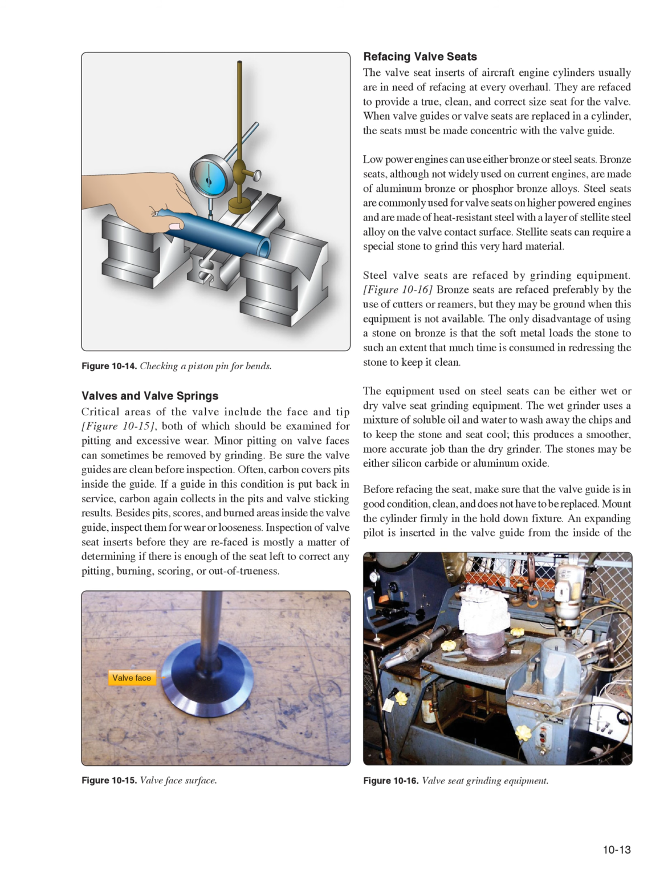Be sure the valve guides are clean before inspection. Often, carbon covers pits inside the guide. If a guide in this condition is put back in service, carbon again collects in the pits and valve sticking results. Besides pits, scores, and burned areas inside the valve guide, inspect them for wear or looseness.